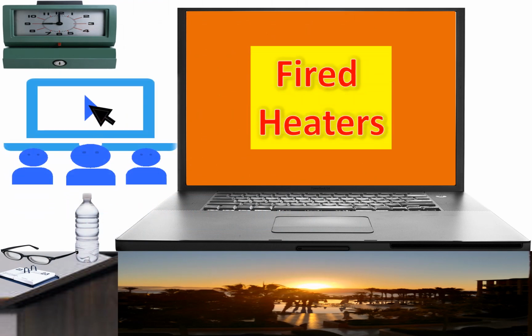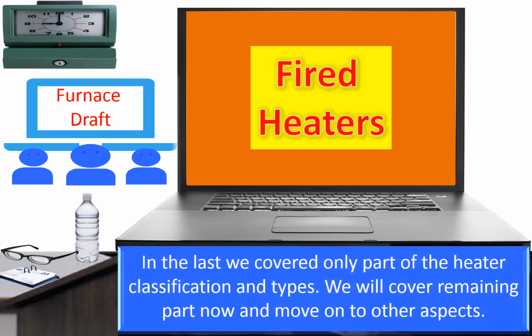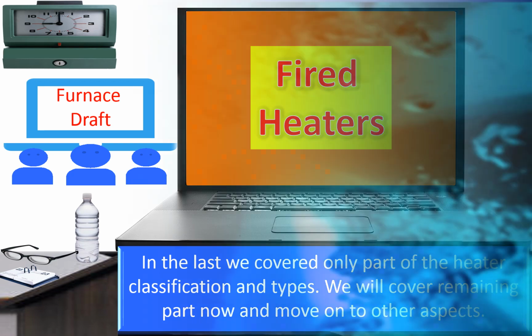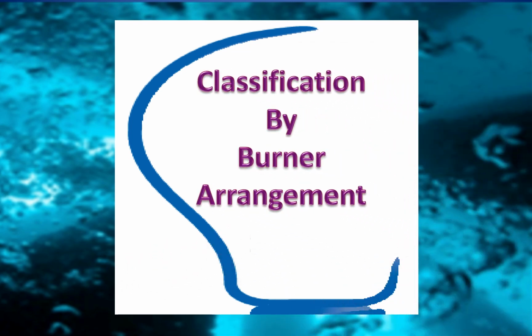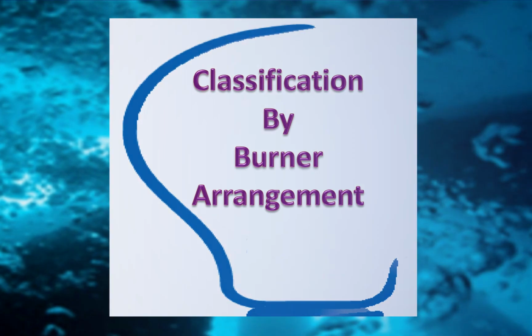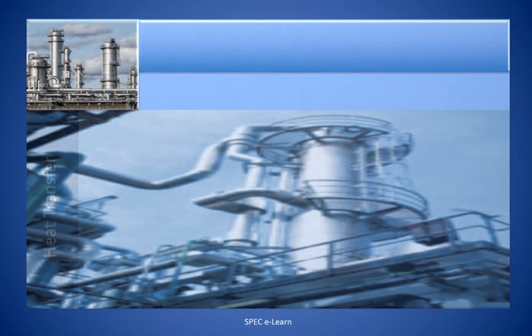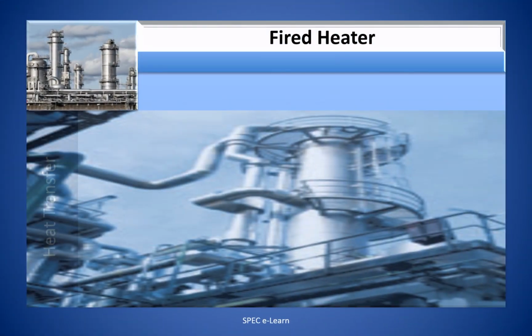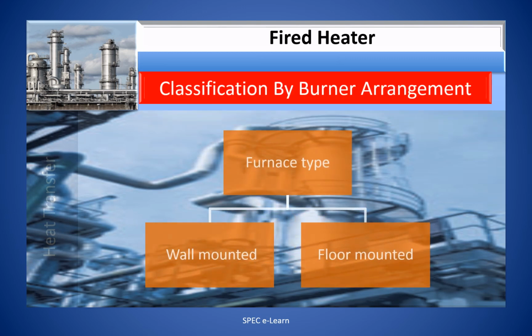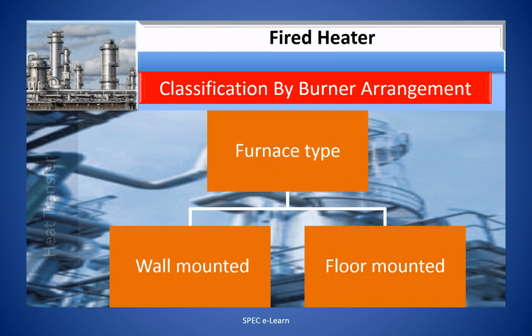Fired heaters. In the last video, we covered only part of the heater classification and types. We will cover the remaining part now and move on to other aspects. Classification by burner arrangement. Based on the burner arrangement, we can classify the furnace as wall mounted or floor mounted.